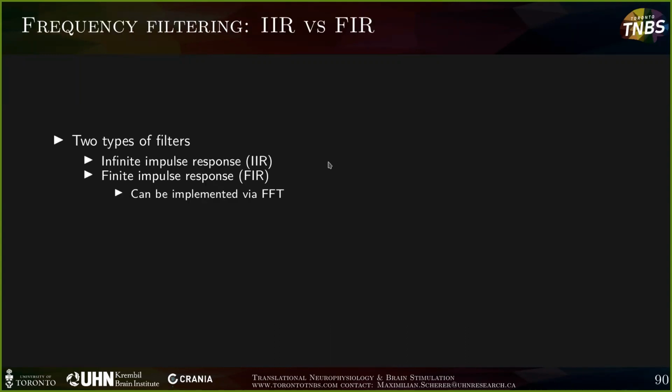And this is going to be the last topic for today's session. I'm running short on time. When you apply frequency filtering, to give the FFT stuff a little more application examples, you can either go with an infinite impulse response filter, or you can go with an FIR filter. And the original filter for getting rid of a specific frequency is the IIR filter.